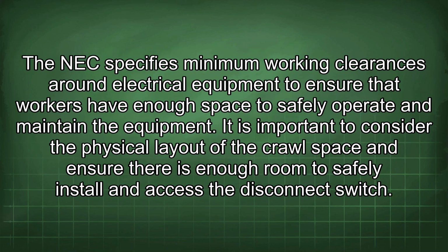The NEC specifies minimum working clearances around electrical equipment to ensure that workers have enough space to safely operate and maintain the equipment. It is important to consider the physical layout of the crawl space and ensure there is enough room to safely install and access the disconnect switch.